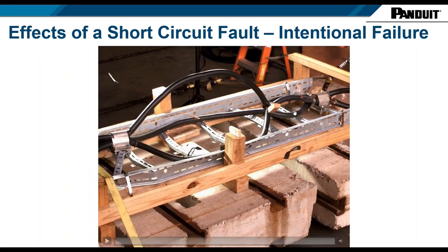So those cables there, 500 millimeters squared copper conductor, class 2 copper conductor, very difficult to bend by hand. And you can see the damage caused purely by magnetic forces. So obviously the cleat on this was underspecified for the short circuit level. But you can see the cables have actually spread by 600 millimeters. They've only been stopped by the side walls of the ladder.